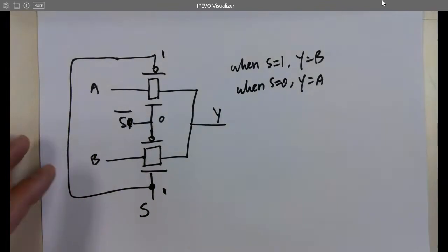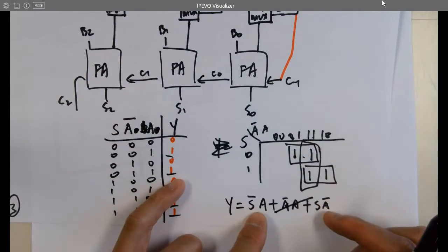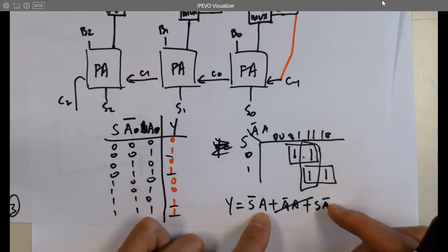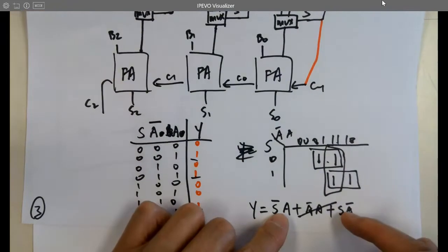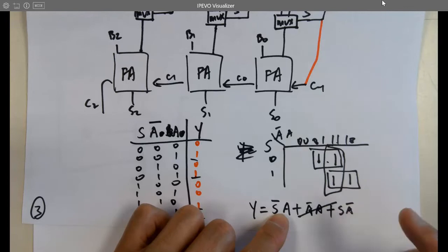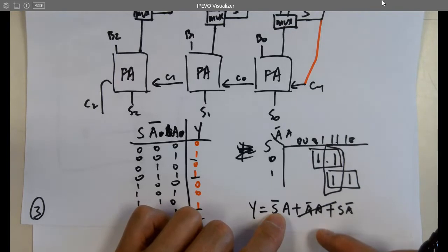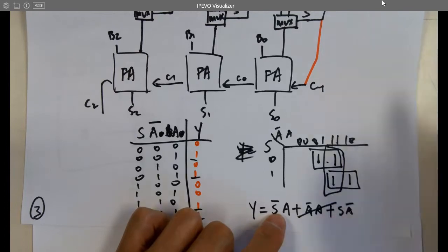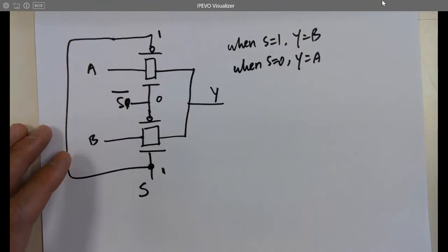So how many transistors do we have over here? You still have to count the inverter in here, right? Every AND gate has 6 transistors. The NAND gate has 4, and you have to invert it. So every AND gate has 6. I did 6 here, 6 here, and the OR gate has another 6, and we're not even counting these inverters. So it's 18 already. So this works a lot better than the other one.